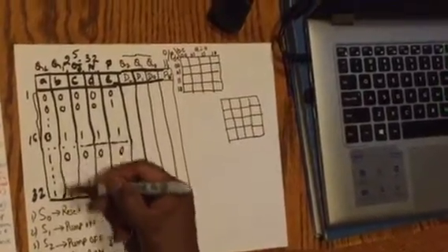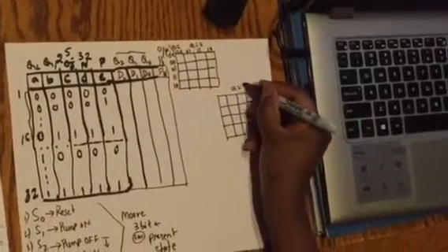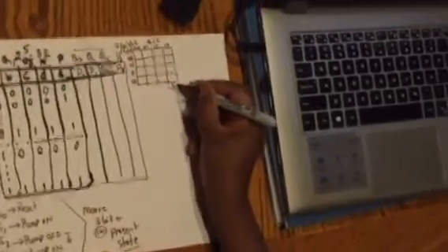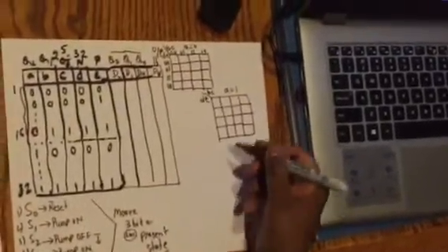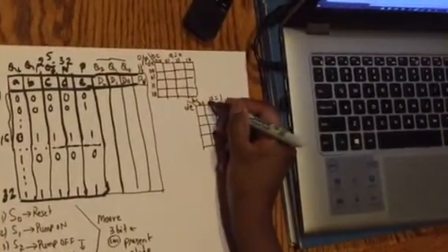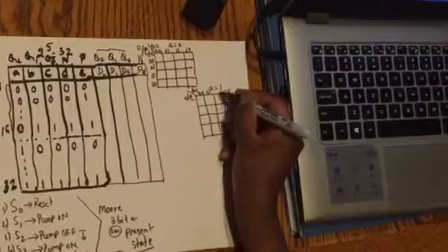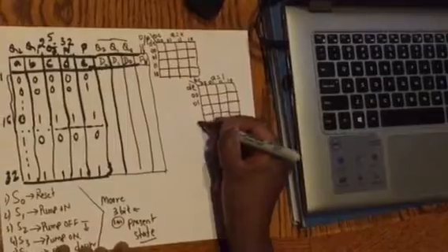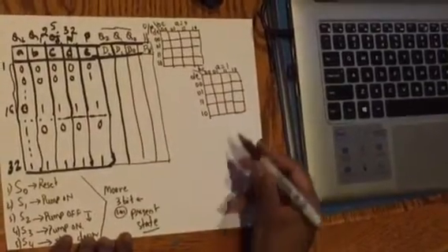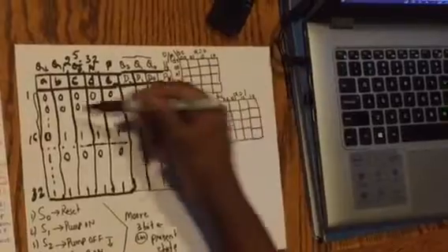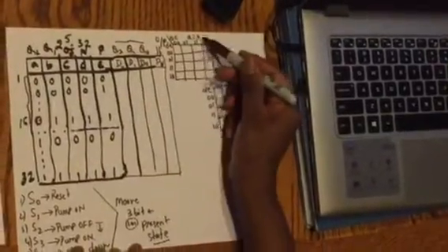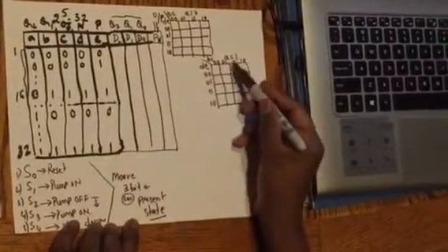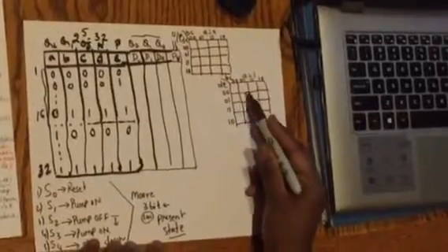Likewise, for the next set of 16 numbers, A is 1 in this map. We write the 4-variable map again, keeping B, C, D, and E as the variables, again running 0, 0, 0, 1, 1, 0, 1, 1 horizontally and the same along the vertical. So basically A is 0 for the first 16 locations, and A is equal to 1 in the second 16 locations.